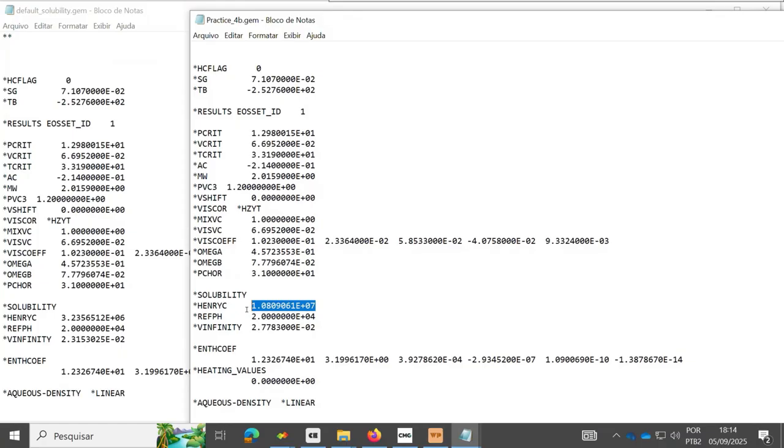However, if you are concerned about representing the geochemical reactions between the hydrogen in the brine and minerals or other gas, it is relevant to be strict with this representation. Okay, so I do recommend you perform this step at the beginning of your modeling process. Try to find lab data close to the initial conditions of your brine in terms of pressure, temperature, and salinity, and do it. It's very simple.